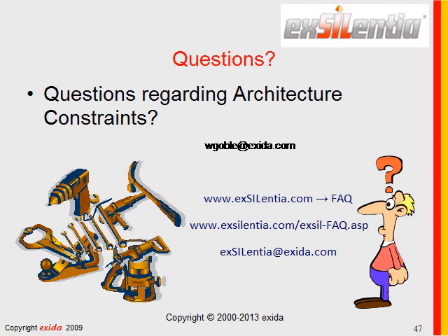But as one comment made earlier, yes, there is fundamentally a big difference. There are other statements in 61511 about quantity of data and manufacturers' quality system audits and so forth, which makes the 61511 criteria stronger than the 61508 Route 2H. So the bottom line is the combination of these. A 61508 certified device with Route 2H data behind it is probably the best you can get.